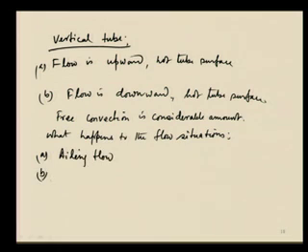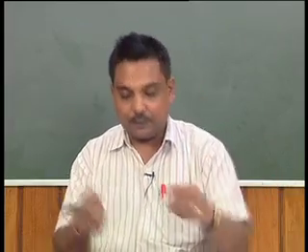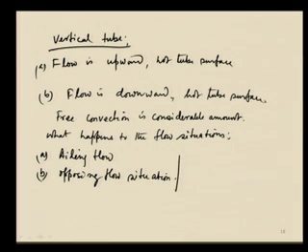In the second case, case B, the fluid will try to go upward, but natural convection will try to make the fluid go downward. So, there will be an opposing flow situation. This kind of flow situation can be encountered when we have flow through vertical tubes.